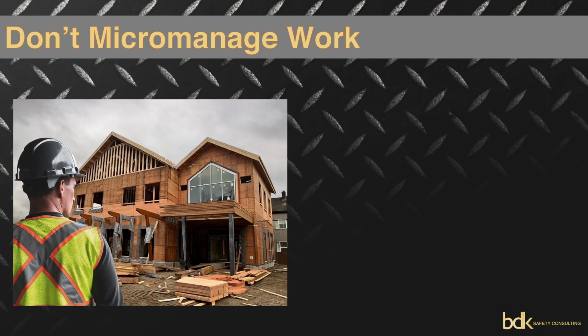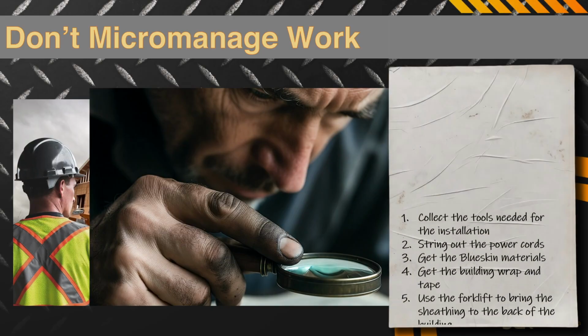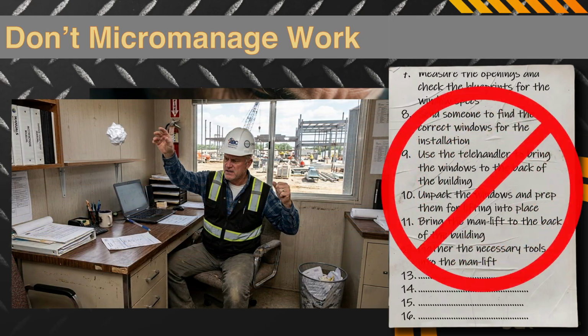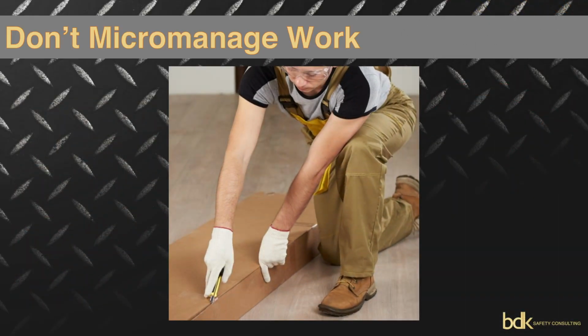The other problem is focusing too closely and going past the tasks right down to the individual steps necessary to do those tasks. This will either end up in a meaningless pile of paperwork or someone being too overwhelmed to even complete the assessment. Don't do it. If you are installing windows and doors, don't break it down to the point where you're assessing the hazard of replacing a blade in a box cutter, right? We will look next at how to break work down into meaningful tasks for a proper hazard assessment.